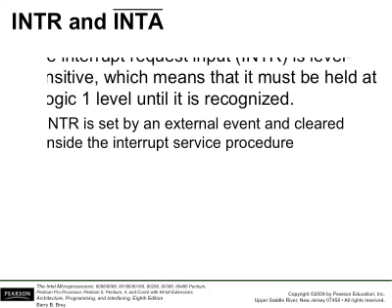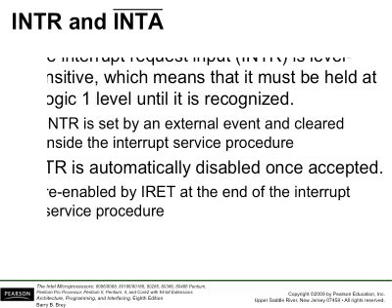INTR and INTA, this pair is used to do the interrupt request and interrupt acknowledgement. INTR is level sensitive, which means that it must be held at logic 1 to generate the interrupt request. This INTR will be set by the external event and will be cleared inside by the interrupt service routine.